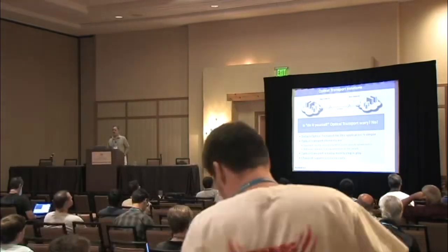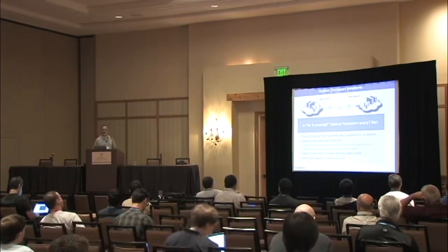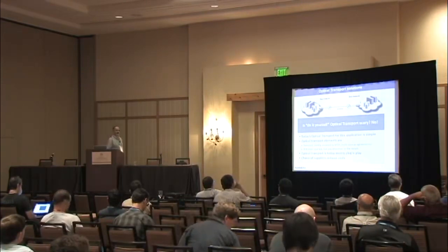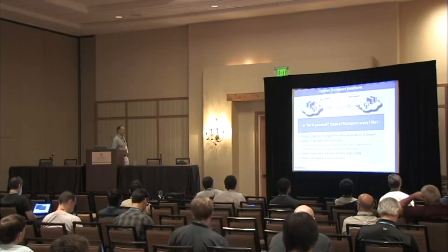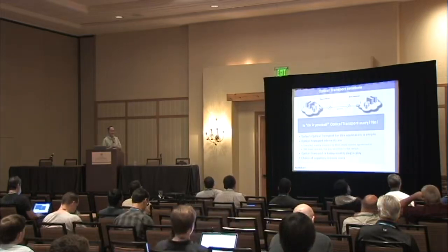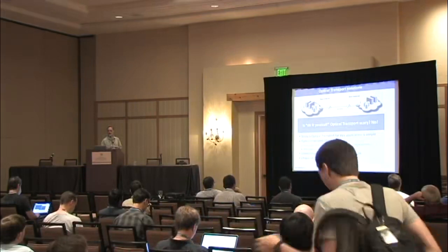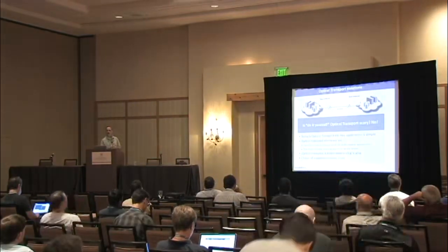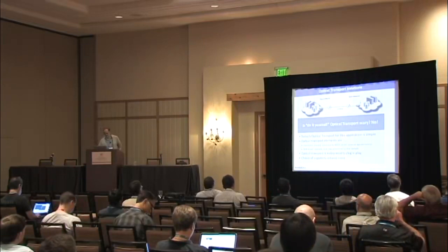You get an SFP, an SFP+, a DWDM SFP+, or an XFP, and you have a very good chance that it's going to work in other types of equipment. You just must pay attention to some details. This type of optical transport is mostly plug and play, and you have such a choice of suppliers that it drives the cost down, so it's beneficial for you to do it yourself, and of course for us.